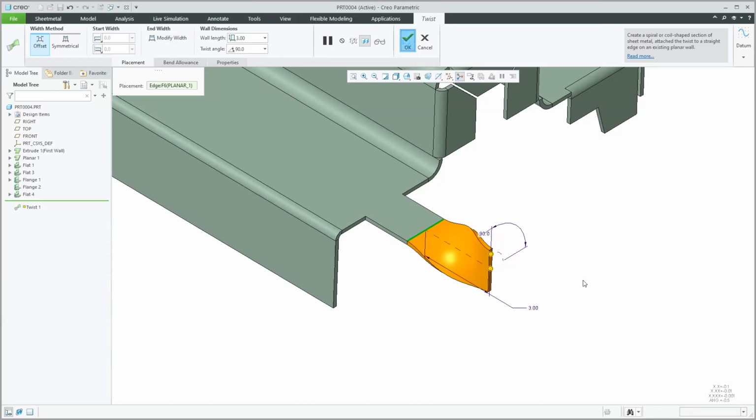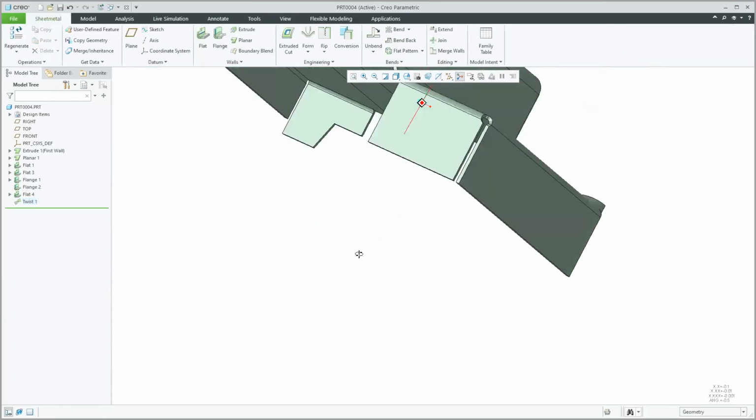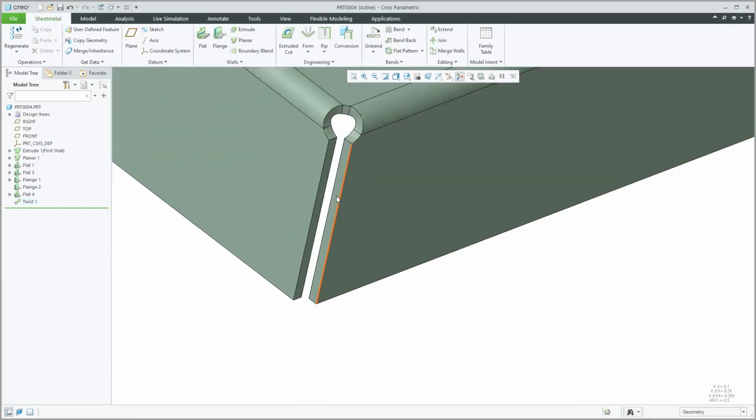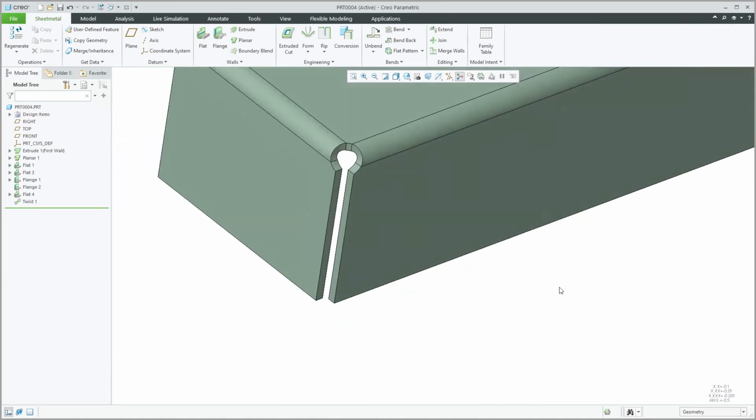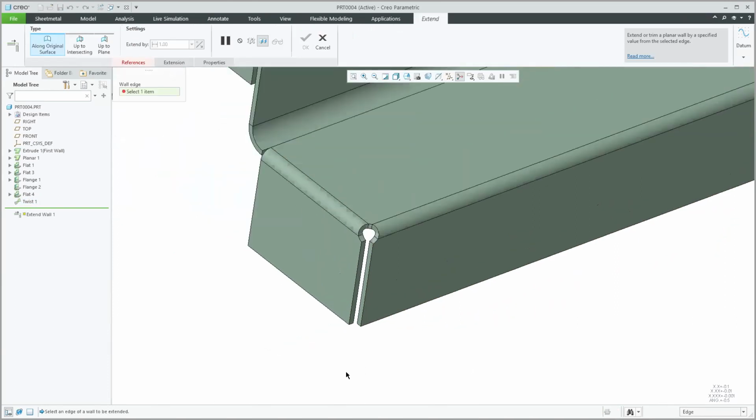And then the extend. What if I need to go through and make a wall a little bit longer? Hey, okay, I left this gap here and I want to extend this out on here. I could go back, of course, and edit definition and change some settings, probably solve that problem. But a little bit faster maybe is just to come over here and extend it. Now, when I extend a wall, I can just pick on an edge. You'll want to pick this edge right here, and I could just extend that out very quickly. All I got to do is specify a value, or I could go up to something that I selected on here. If I want to do those, I want to extend this edge right here. And so again, it's going to now ask me for a value.